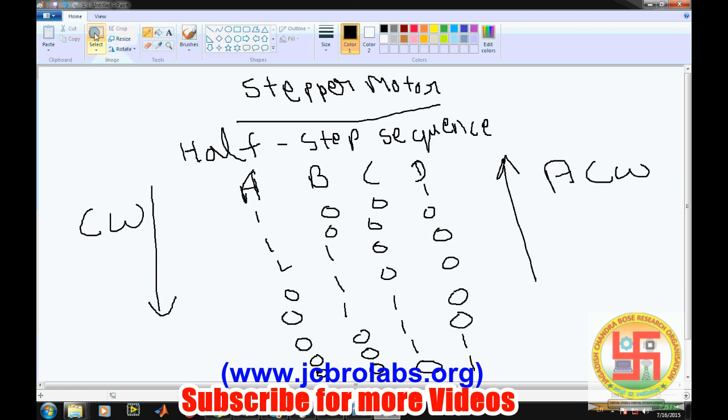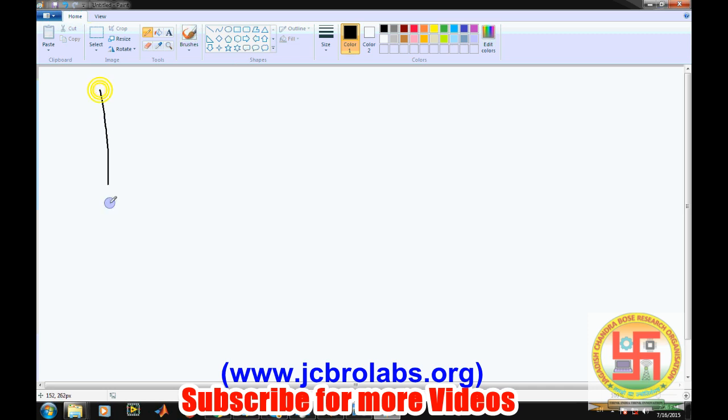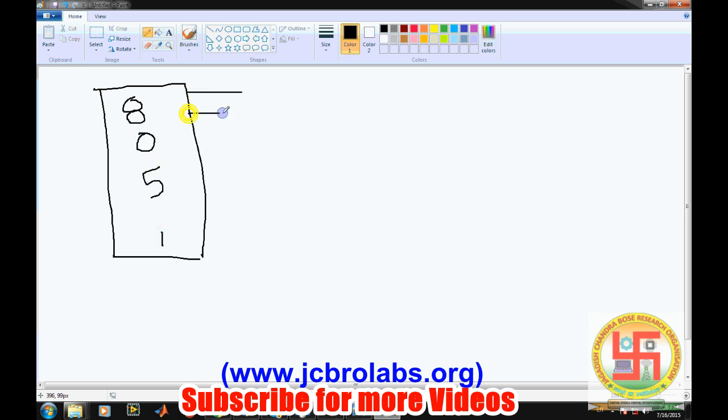Now let's make the connections to interface a unipolar stepper motor to the 8051 microcontroller. We will have an 8051 microcontroller here, and we will be using the 4-step sequence. So for this 4-step sequence, we will connect P1.0, 1.1, 1.2 and 1.3.